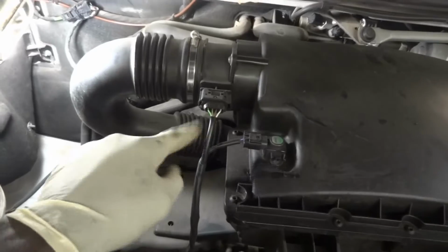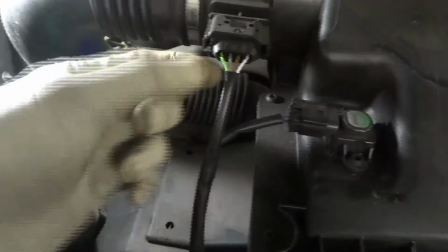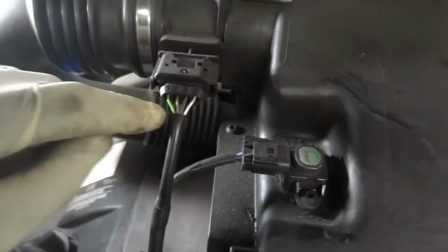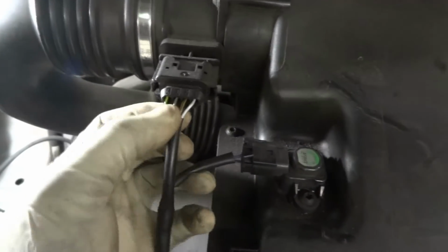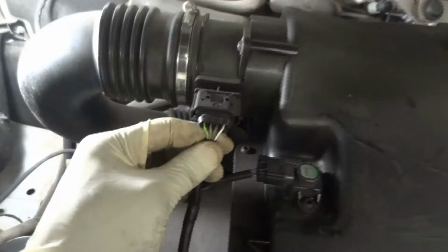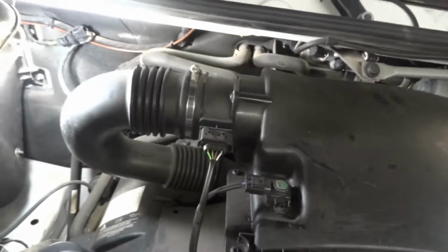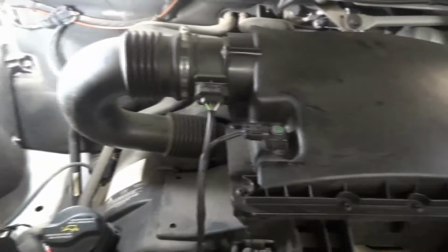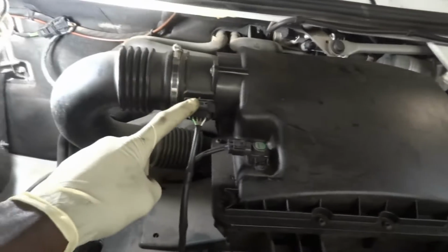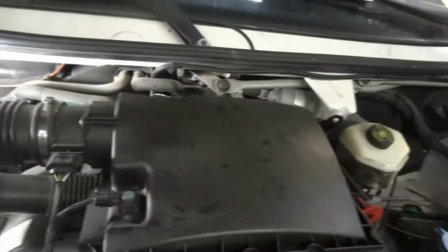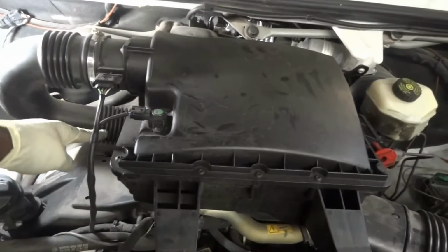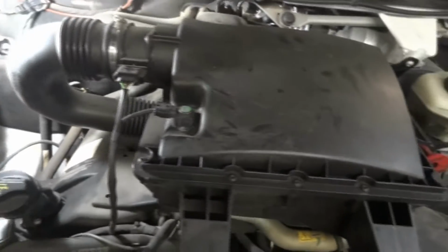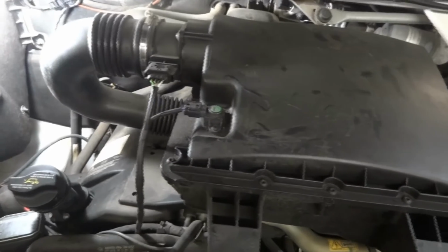I'm gonna make sure we have power and ground here. I believe this green wire with a yellow tracer is our signal wire, and then these other two, I believe, are ground. And actually we can pull out the wiring diagram so we can see this. So let's go and do some checks here. I'm gonna bring the lab scope. If everything checks out okay, we're gonna remove this air filter box so we can look at that gasket down there. It looks a little suspicious. So let's go back in the car and hook up our lab scope.